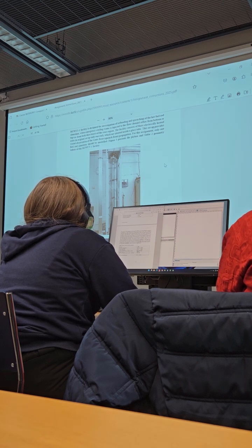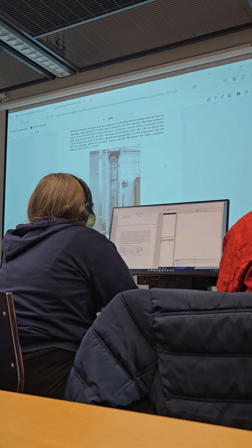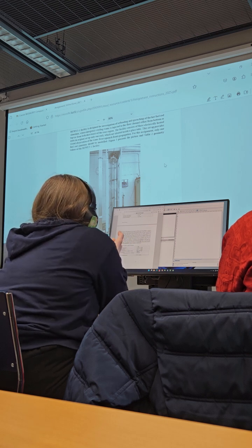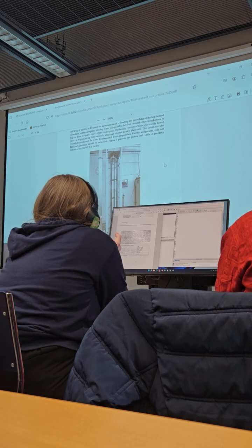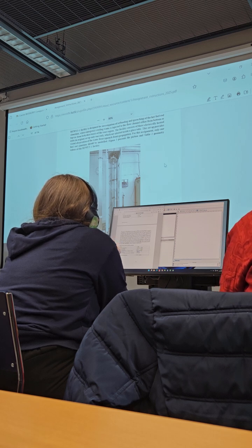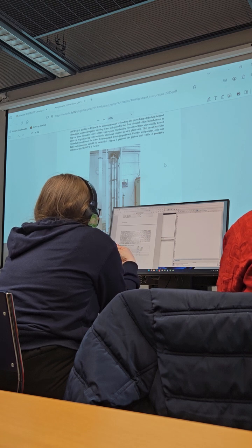But it is also a balance between cooling down and, at the same time, if you make the quench front propagation very fast, it can lead to a kind of shock wave, because when the water touches the surface of the really hot fuel rod, it starts evaporating. A lot of boiling, a lot of vapor will generate in a short time period, then pressure goes up. So they try to balance.